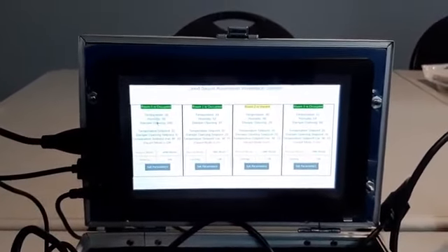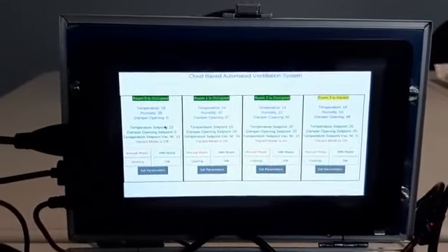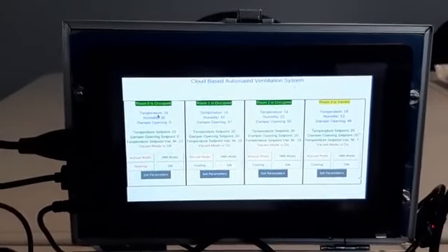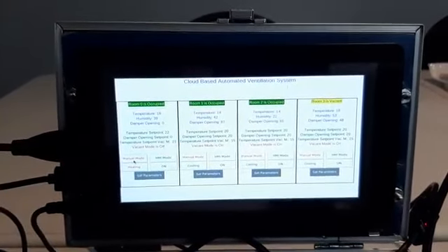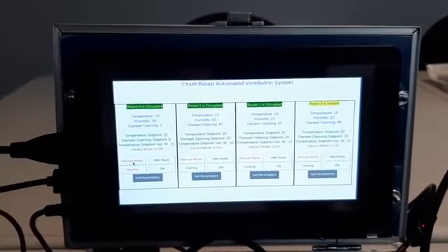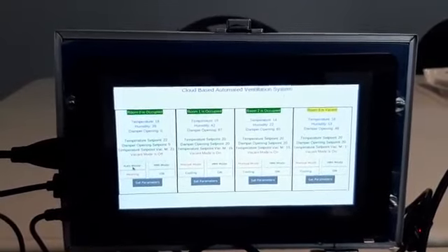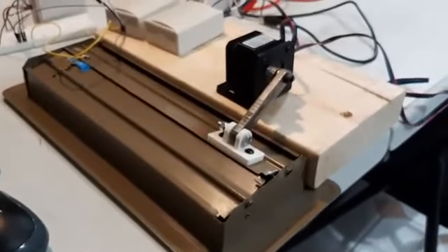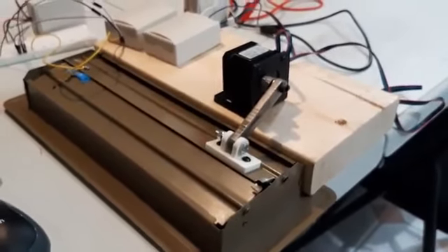At the moment, our temperature is 18 degrees and the temperature set point is 22 degrees. So we can assume that we want to put it in heating mode. The set point is 22, but the temperature is cold, so the temperature is lower than the set point. If you are in heating mode in auto mode, the damper has to be opened. So I select auto mode, and we expect that the damper opens. Then we are waiting for the damper to operate, and we are expecting that the damper opens because it is in heating mode.